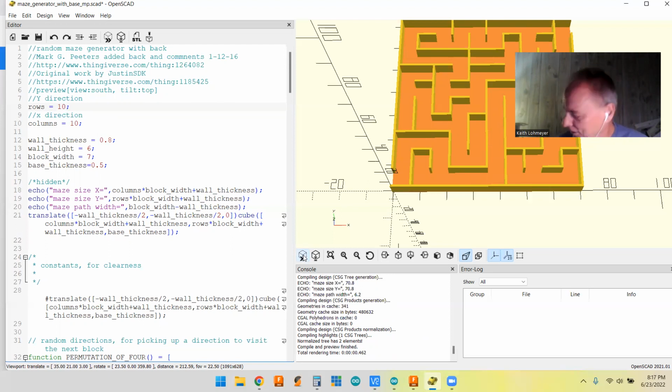That's why I ended up with 3 of them all in one right after the other. They're so easy to make that you just get these files and let your printer go at it. But like I said, the big thing is you want your wall thickness to be 2 times your nozzle. So if you got a 0.4 nozzle, yeah, that's what you want.